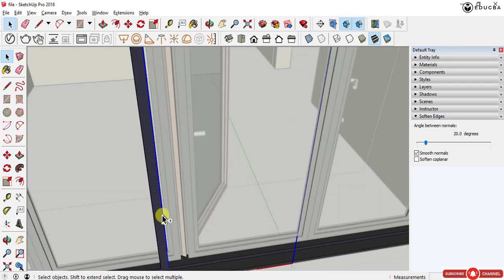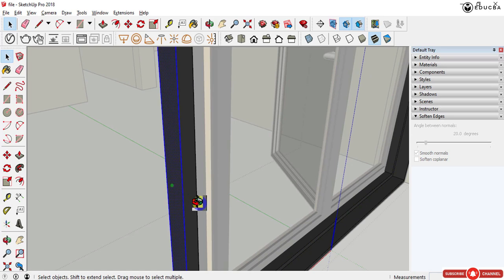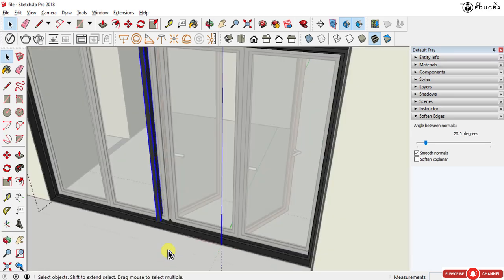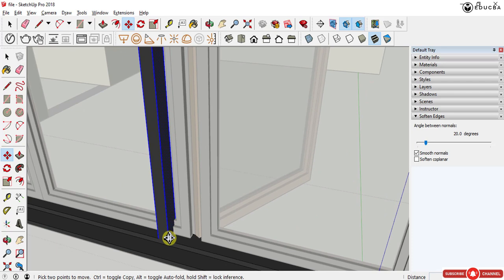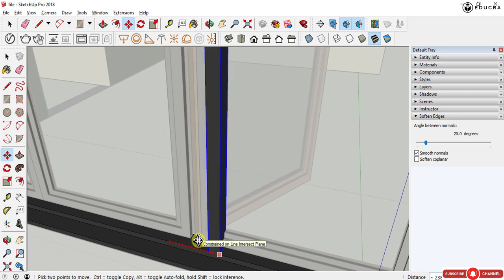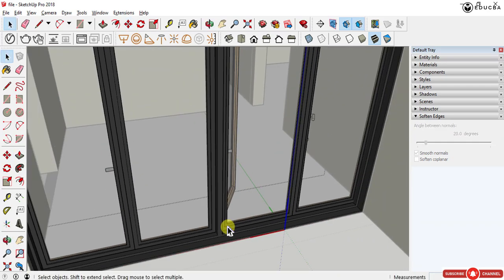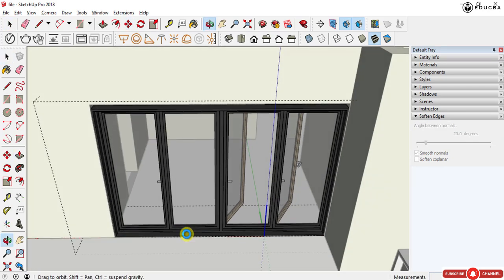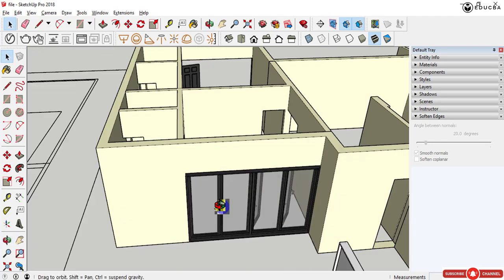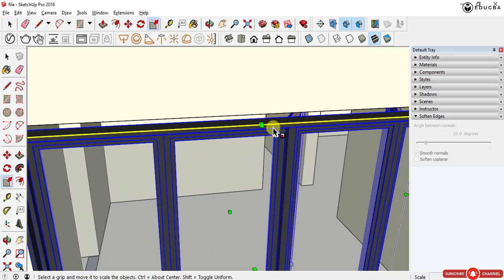At such points, instead of clicking or selecting, you can simply select this surface and move it. So the complete geometry moves. I'm going to keep pressing the shift so that I don't lose the point, and click. You get two set of doors operating as a French window. I'm going to click this again, scale it up.